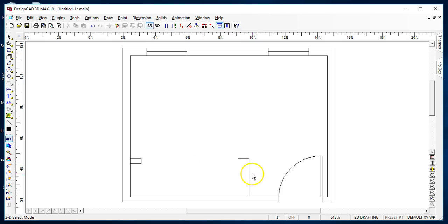I need to make this wall thicker. Because I drew it as a continuous line, I can parallel it. See that? It's continuous. So I can parallel it by clicking, holding this down and getting the parallel tool. Partition walls, closet walls, pantry walls, they're all 4 inches. So I type in 4 inches. Click on this and go inwards. See, I can go outwards or inwards. Go inwards, press the left mouse button, and then we just simply need to close this up. So we get the ortho tool, right click, enter.